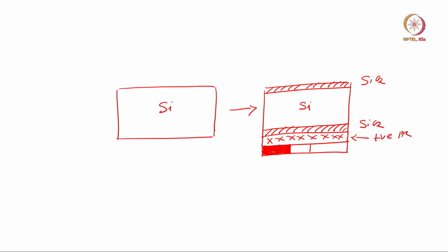We will expose the photoresist after the soft bake is done. Soft bake is generally performed at 90 degrees centigrade for 1 minute on a hot plate, but it also depends on the data sheet and what kind of photoresist you use. So, you can always refer to the data sheet before you optimize your photoresist.